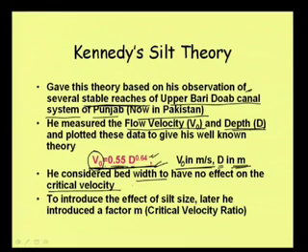And then, to introduce the effect of silt size: as you can observe in this formula, he is saying that this velocity is the critical velocity where no erosion and no deposition will take place, and depth is the only parameter on which he is deriving this velocity.